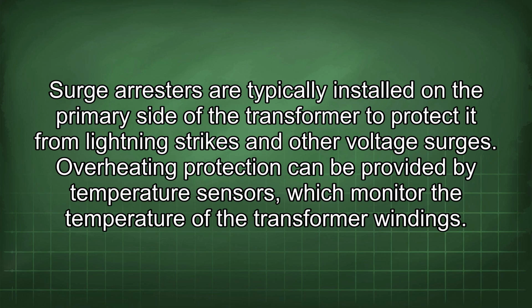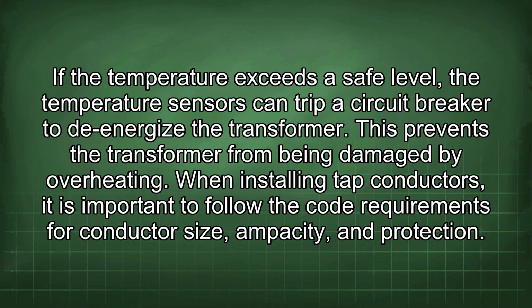Overheating protection can be provided by temperature sensors which monitor the temperature of the transformer windings. If the temperature exceeds a safe level, the temperature sensors can trip a circuit breaker to de-energize the transformer. This prevents the transformer from being damaged by overheating.